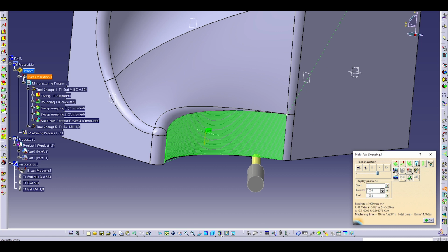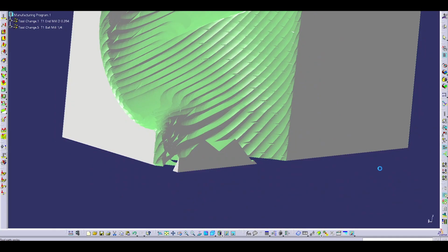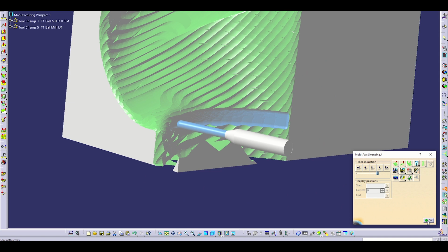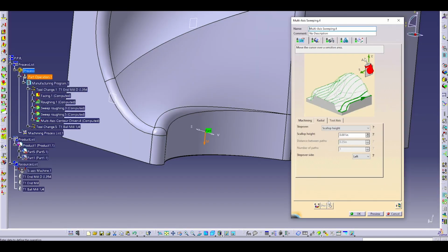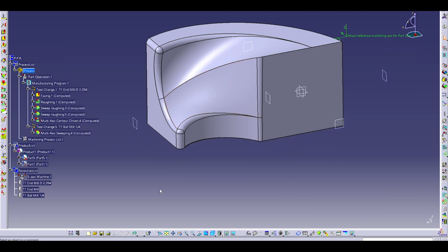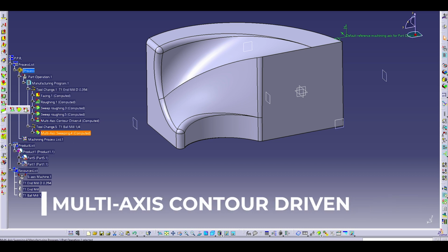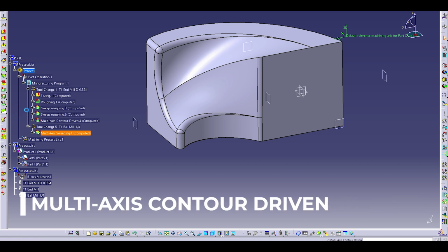So I'm going to change the machining axis there to downwards, and you'll see that it'll change it from going down to up, now to go up to down. So that's pretty big. Kind of understanding those different axes will help you a lot with getting the tool right on the part and being able to move that tool around however it is needed to get the best contours.